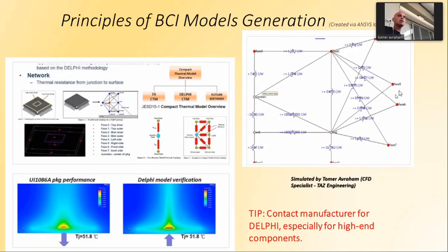3U PCB, and then you have two choices. This 3U PCB is small; it's about 7 centimeters wide. Four of them are real estate of the FPGA. And now you need to do a thermal analysis, and the most dissipative component is the FPGA. It dissipates 25 watts.